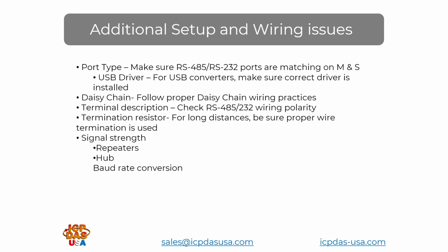Some RS-485 ports are also partially used with RS-422 wiring. So sometimes you need to connect the RX plus and the TX plus to the data plus of the RS-485, and then the RX minus and TX minus to the data minus of the RS-485 terminal.